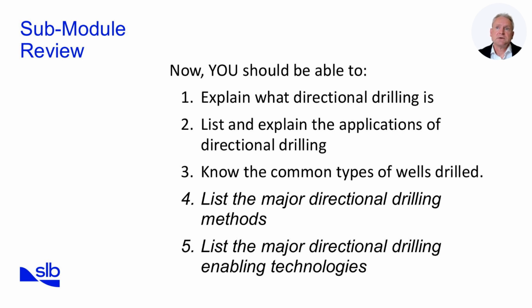We then moved on to the different modern applications. These included environmental, where we used ERD techniques for difficult to access resources, structural developments such as offshore platforms and pad drilling, production field developments such as multilaterals and SAGD, and unconventional reservoirs. Other applications can include gas storage and river crossings. This concludes the first sub-module on applications, objectives, and limitations.